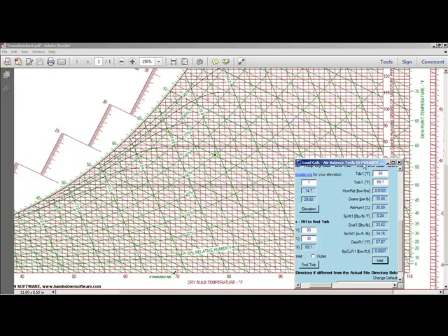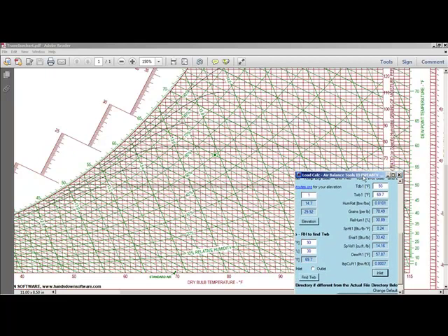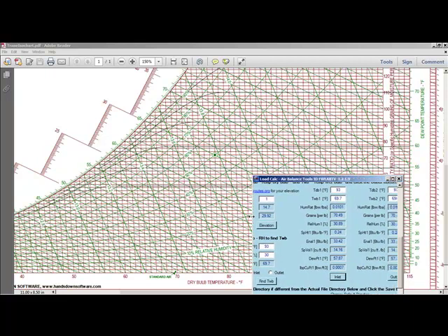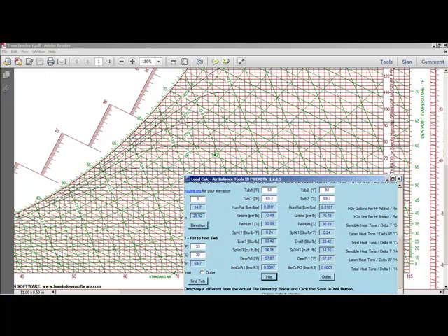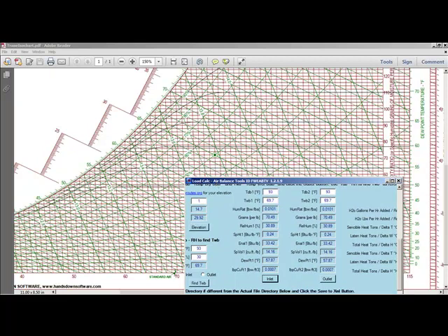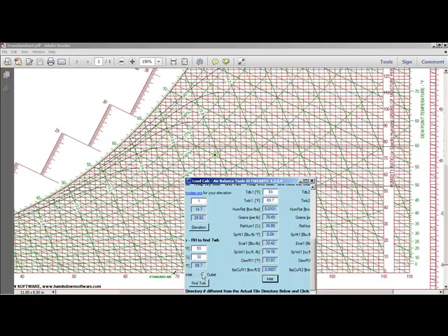And we're going to add, I don't know, let's go ahead and add about the removal of about 10 grains per pound. And let's go to 70, 71, 72. So let's say our outlet is 72 at about 50% for outlet.